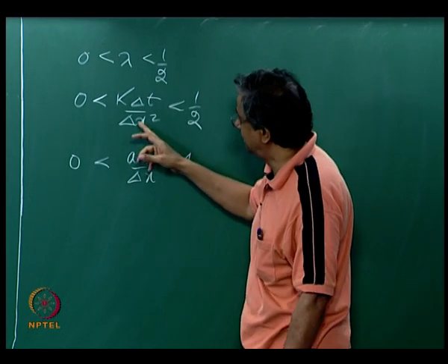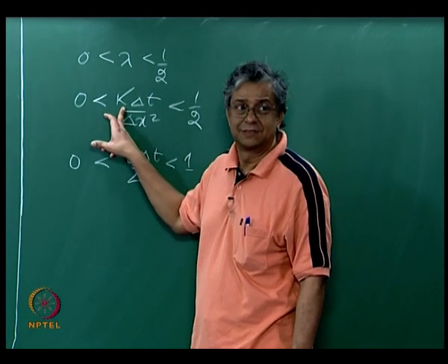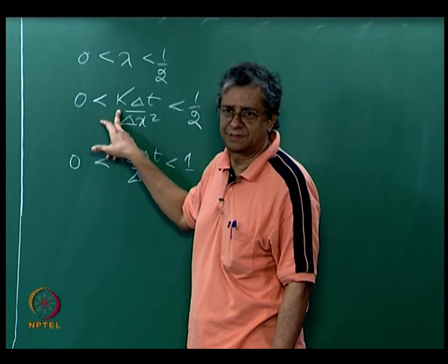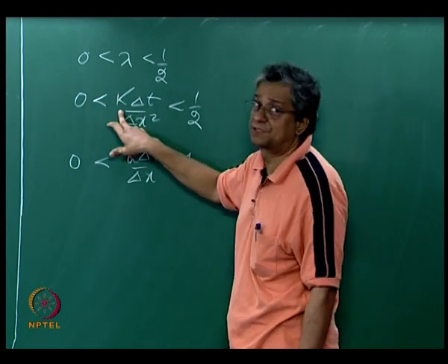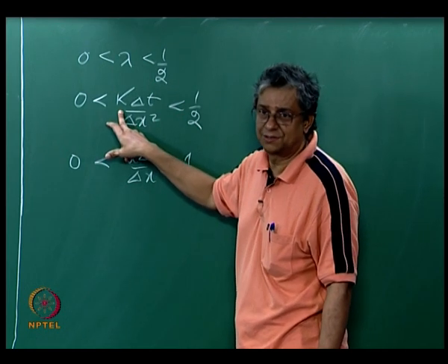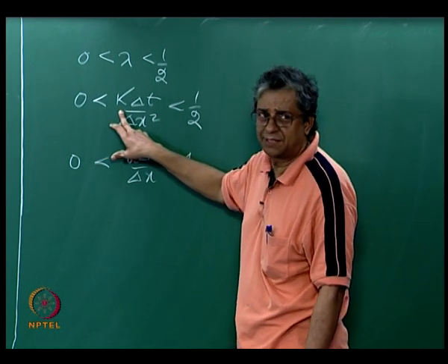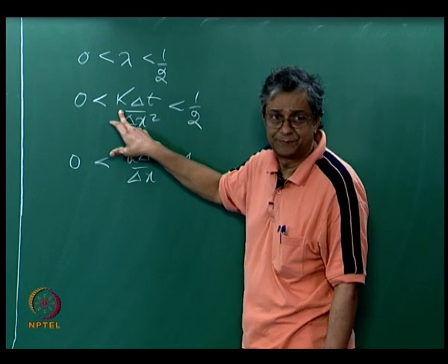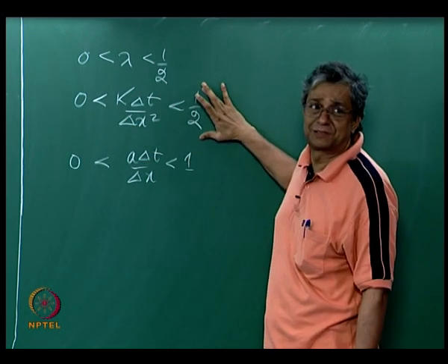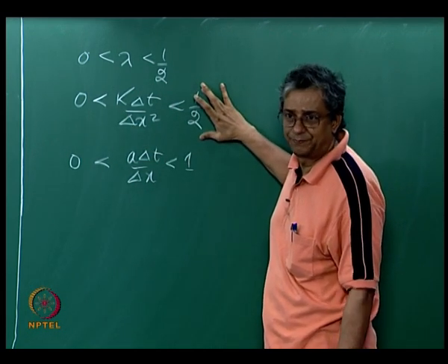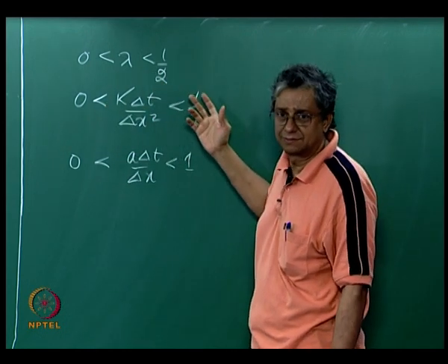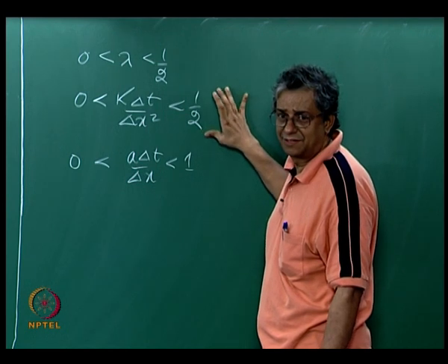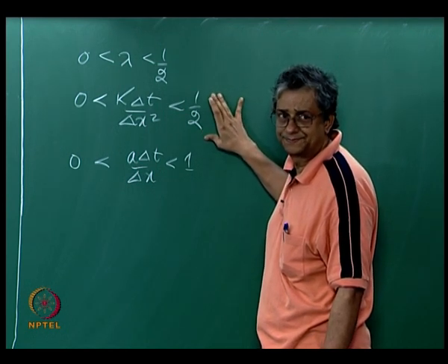For the heat equation it's kappa, but if you add it as artificial dissipation, it would be mu2. If you make the artificial dissipation so large that mu2 dominates, for all practical purposes it becomes like heat equation, then this is really the stability condition that you need to be worried about. So if A is of the order of 1 and kappa is of the order of 1 million, then this is really the stability condition that you have to be bothered about.